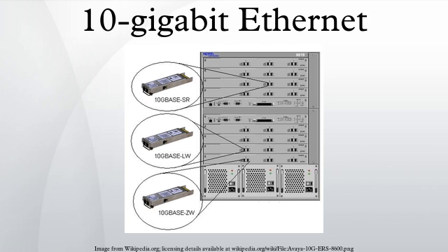802.3ap implementations are required to operate in an environment comprising up to 1 meter of copper printed circuit board with 2 connectors. The standard defines 2 port types for 10 Gbit/s and a 1 Gbit/s port type. It also defines an optional layer for FEC, a backplane auto-negotiation protocol, and link training for 10GBASE-KR where the receiver can set a 3-tap transmit equalizer.